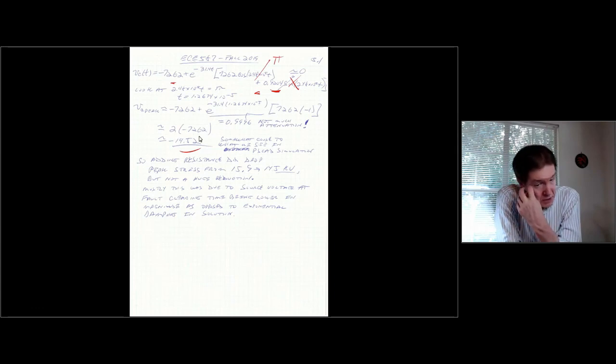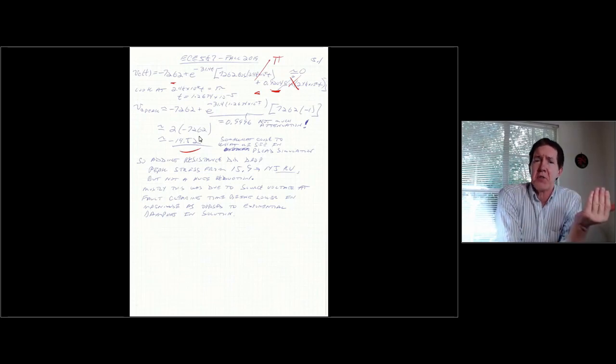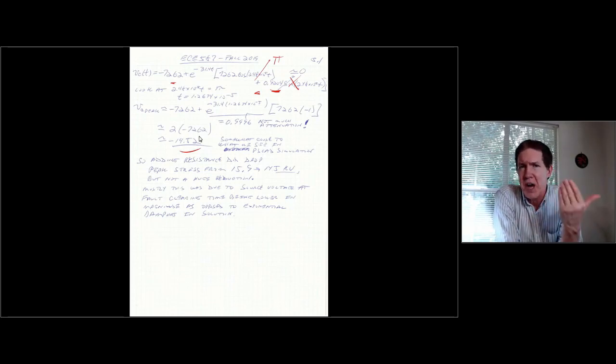But what you would do is basically work with a second order differential equation. You choose the dominant R and the dominant L and the dominant C, and you go with that, and you get close. Usually that's good enough, given the uncertainty in the field parameters, as far as doing something by hand. And then if you want to do something more accurate, you could use the computer simulation for that.